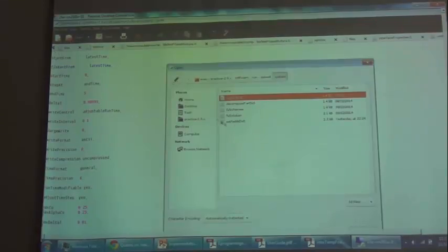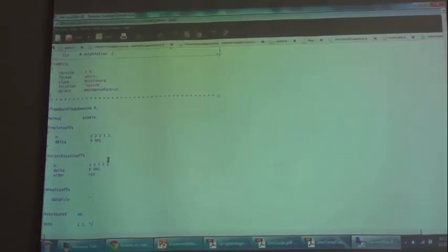You can also specify the intervals at which the time directories have to be written, and you can specify the maximum Courant number, the global Courant number. That will basically be important in some of the cases wherein it's sort of expensive. Decompose part basically contains the methodology in which the partition will be done, and in this method I'm using Scotch.